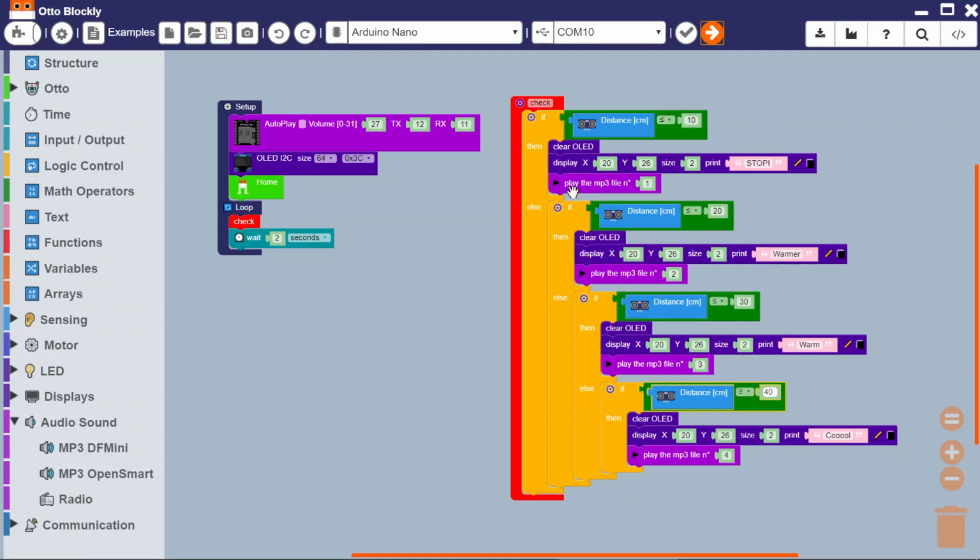Okay, so you've got a 500 millisecond delay there. This is going to mess up the neopixels, and it will mess up motion as well. But if Camino takes that out, these files don't need that delay. In fact, all the commands don't need the delay really, except the initialization, which happens in this block here. Okay, so that's where any delays to the DF Mini should be placed.